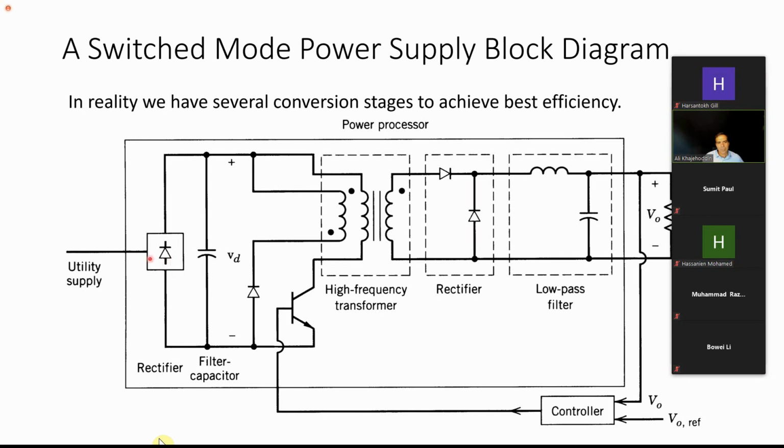So you're going to need some rectifier. You create a high voltage here, and then you use some kind of switching actions and topology and a transformer. So you convert that high voltage to some kind of AC. So you can use a high frequency AC transformer. The size of this transformer, because it's high frequency, is going to be very small.